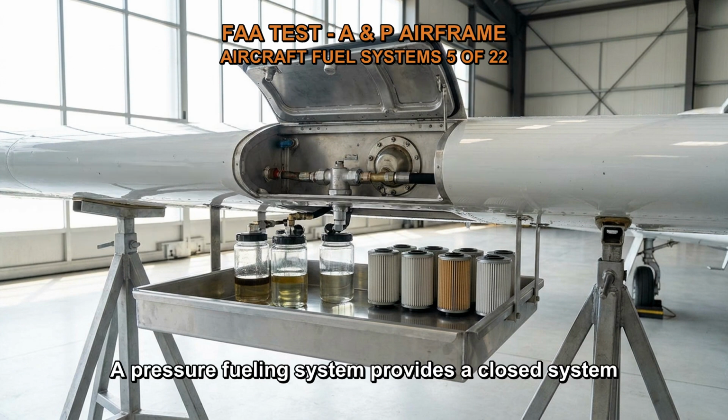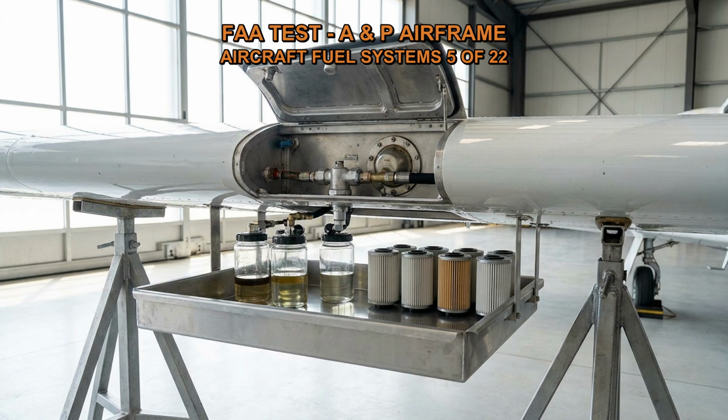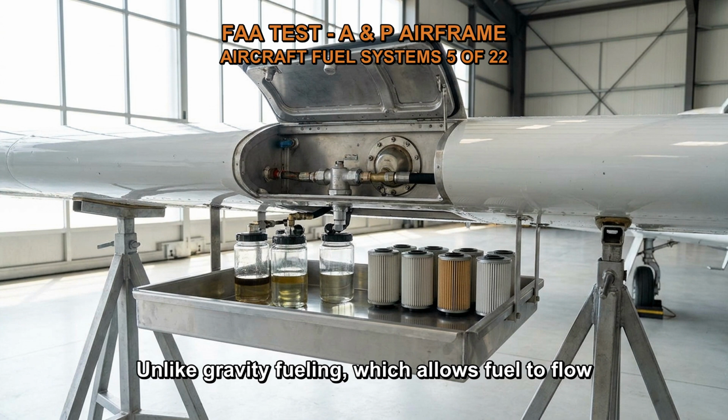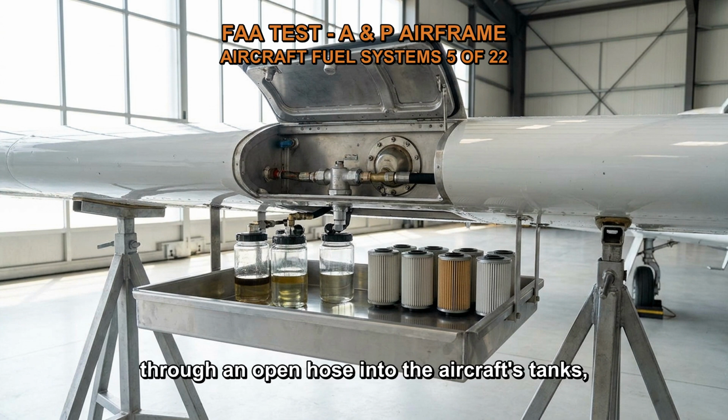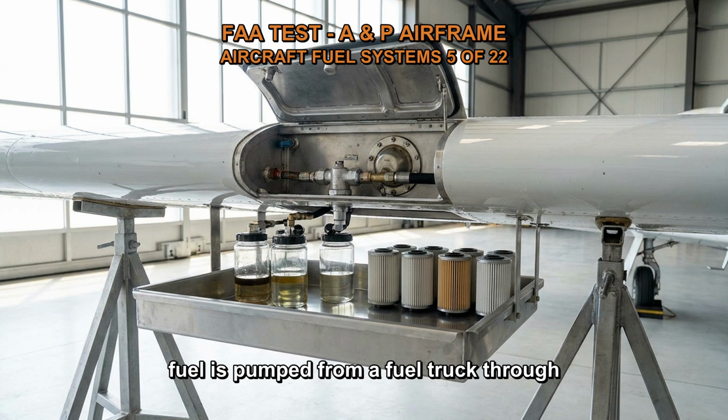A pressure fueling system provides a closed system for fueling an aircraft, which helps to reduce the chances of fuel contamination. Unlike gravity fueling, which allows fuel to flow through an open hose into the aircraft's tanks, pressure fueling uses a closed system in which fuel is pumped from a fuel truck through a sealed hose into the aircraft's tanks.